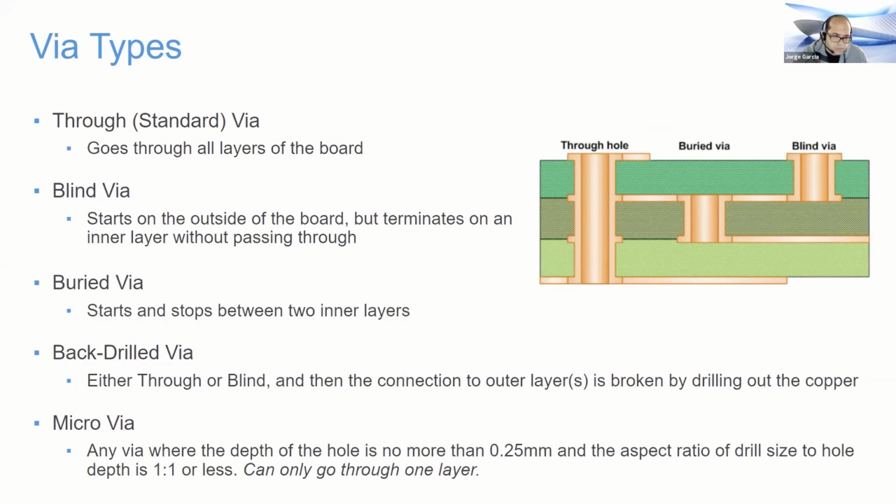Now there is a question about custom milling operations for slotted pads. Typically, at this point, for most designs, unless they're very complicated mills or you have a lot of them, it doesn't really add a lot to the cost, because they're already doing a milling for the board shaping operation.